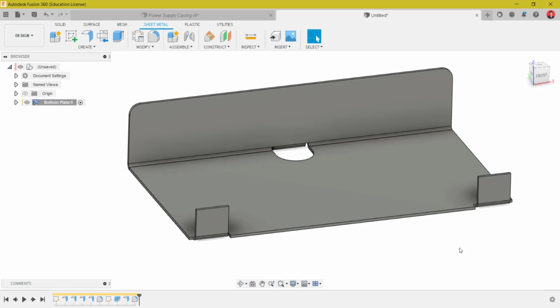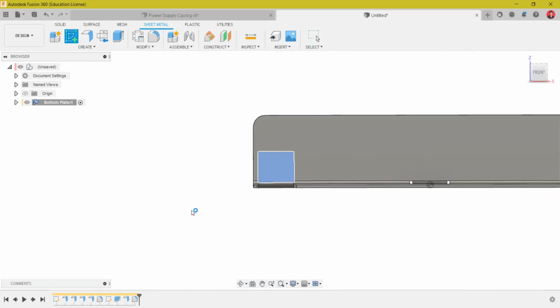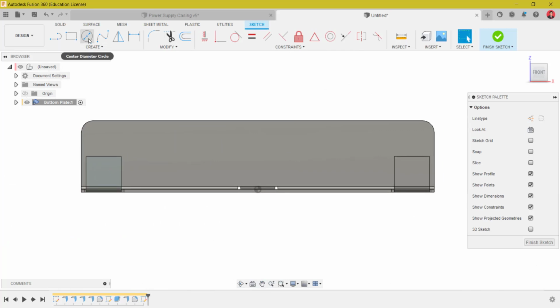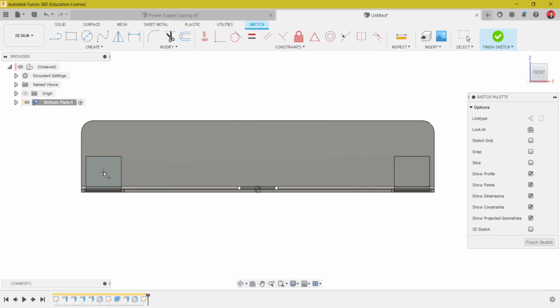Okay, and then create a sketch which represents the holes from the small flange, both of them. Use the horizontal constraint to keep them at the same horizontal distance and also the dimension of the position of this hole.